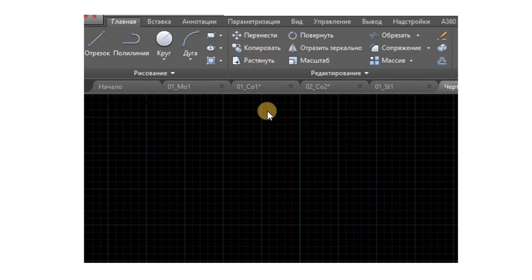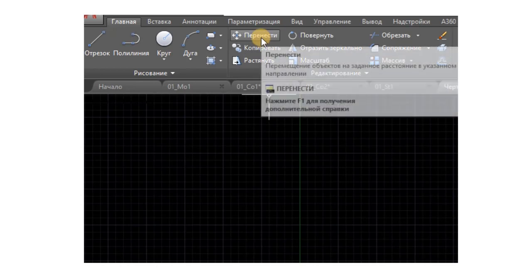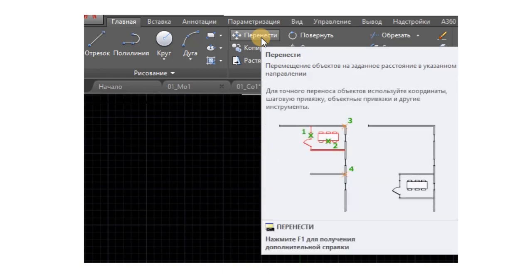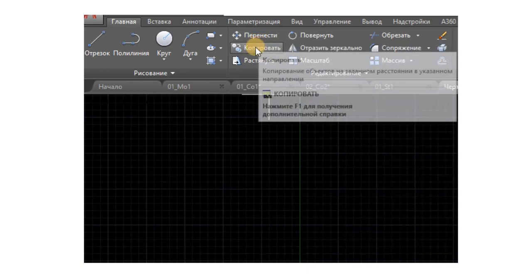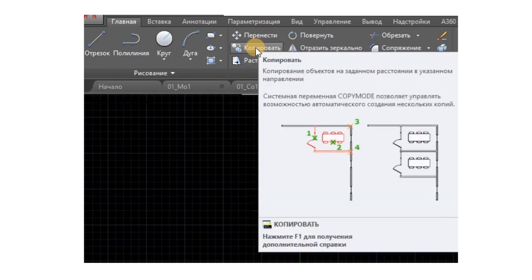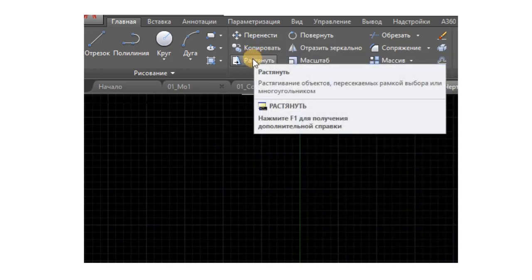After you start the command and select the objects to be edited, AutoCAD prompts you for two pieces of information. Specify base point or displacement, specify second point, or use first point as displacement. In a subtle way, this prompt says that two possible methods exist for you to specify how far and in what direction you want objects copied, moved, or stretched.